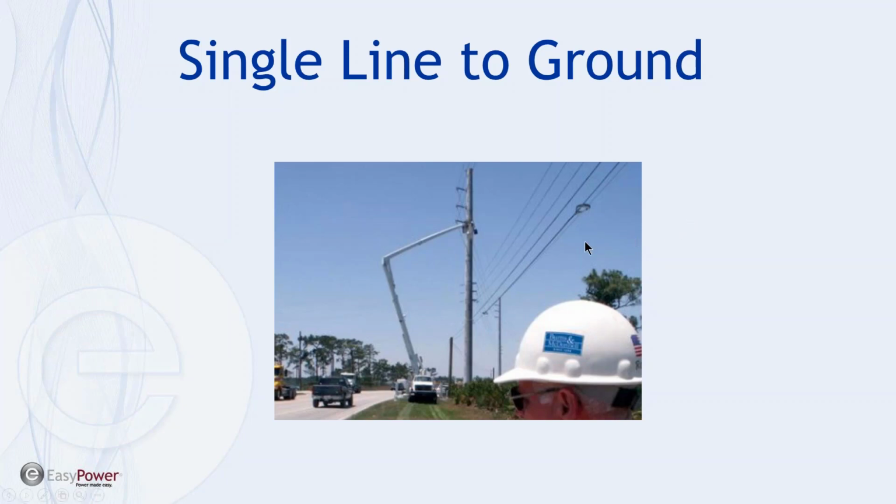You'll notice once you get into the tools that there's the ability to elevate that calculation and carry that incident energy into a two-line to ground fault as well as a phase-to-phase fault. And these are estimates because they're basically multiplication factors based upon the single line to ground fault model. So Saeed, I'm not sure if I've got the question right, so you may need to contact me directly. Does EasyPower,